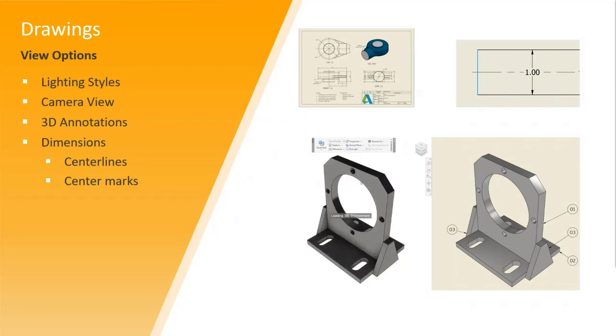There is a new drawing view option available to repurpose the camera view and 3D annotation created in the 3D model. Center line and center mark with extended line now break when intersecting with a dimension. This makes it easier to read the dimension value.